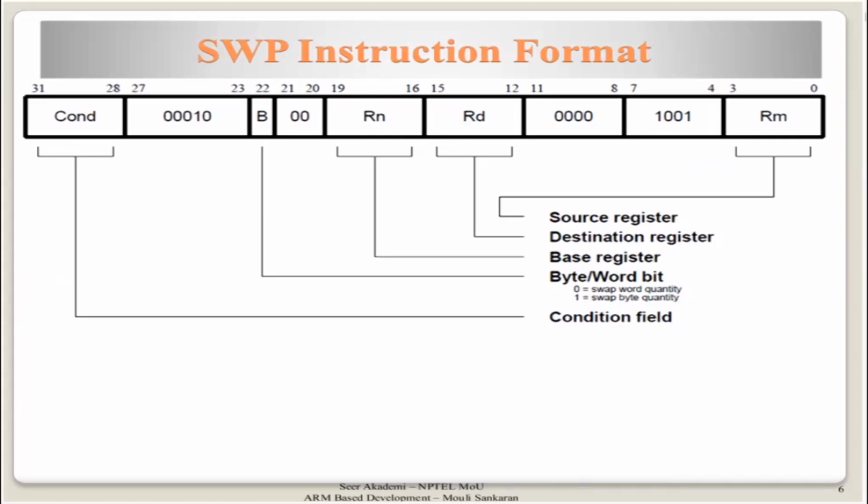This is very important, as we have seen so many formats so far. Here you could see that the opcode, or the special bit pattern after the 4-bit conditional flag, is increasing. If I remember correctly, data processing had only 00 and data transfer had 01.